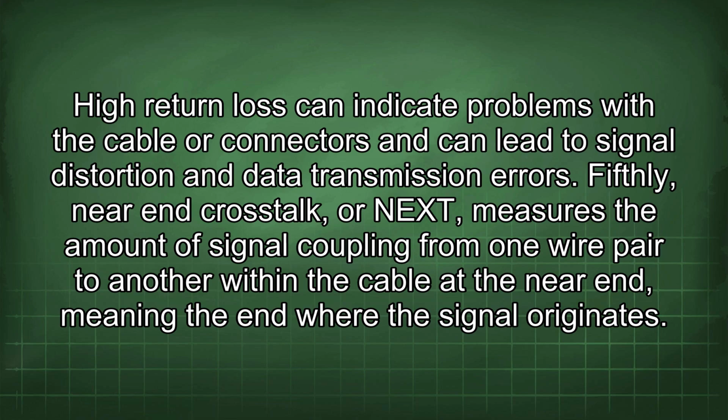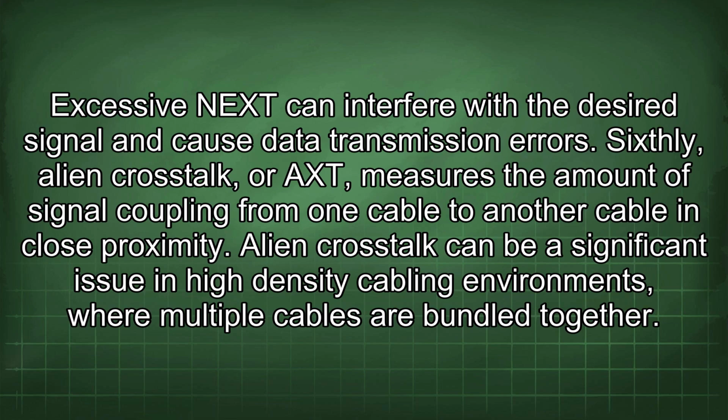Fifthly, near-end crosstalk, or NEXT, measures the amount of signal coupling from one wire pair to another within the cable at the near end, meaning the end where the signal originates. Excessive NEXT can interfere with the desired signal and cause data transmission errors.